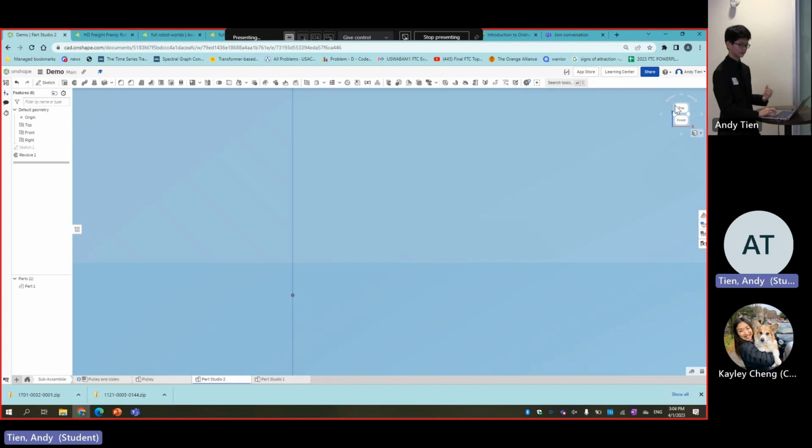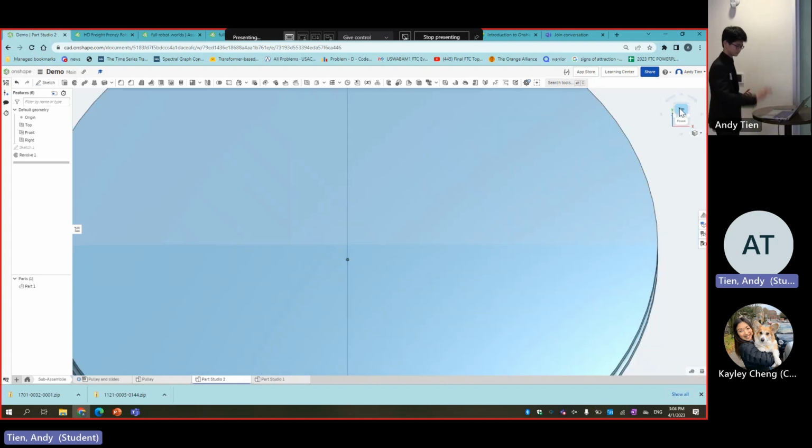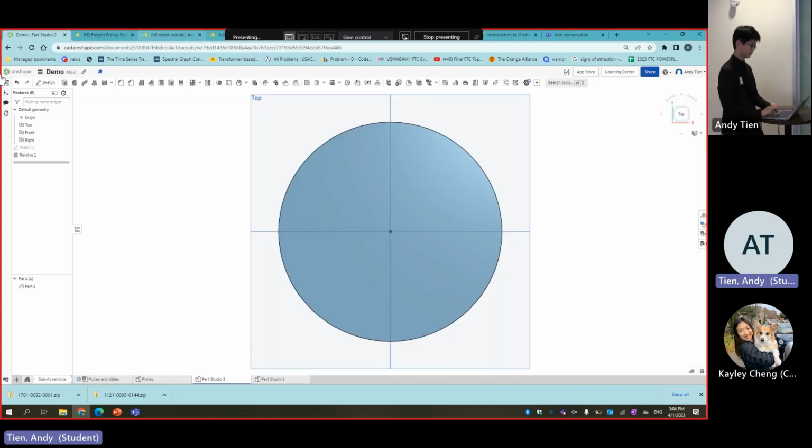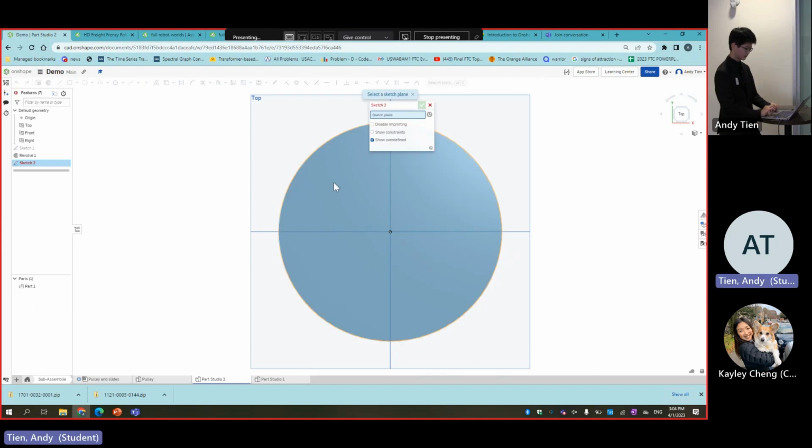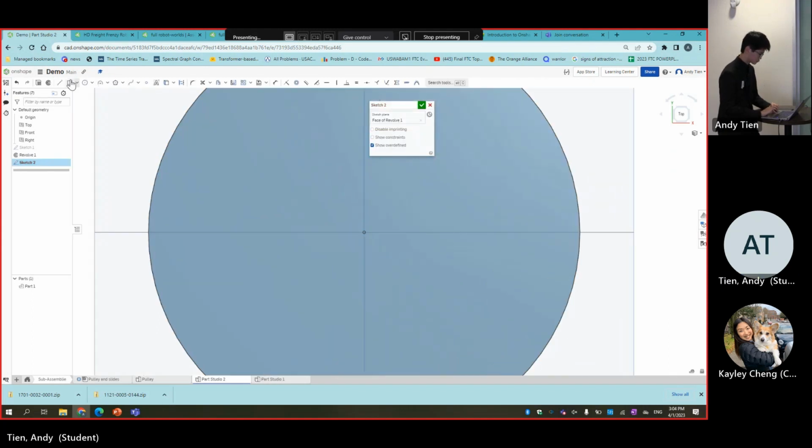And now we're going to talk about how to make holes, right? So once again, first I'm going to do a sketch, and I'm going to sketch out a rectangle. What this rectangle is for, we're not trying to cut a rectangular hole. This is just for defining the positions of the holes, because many of the parts you're going to be buying come with hole patterns, and those hole patterns are usually defined in rectangular lattices.